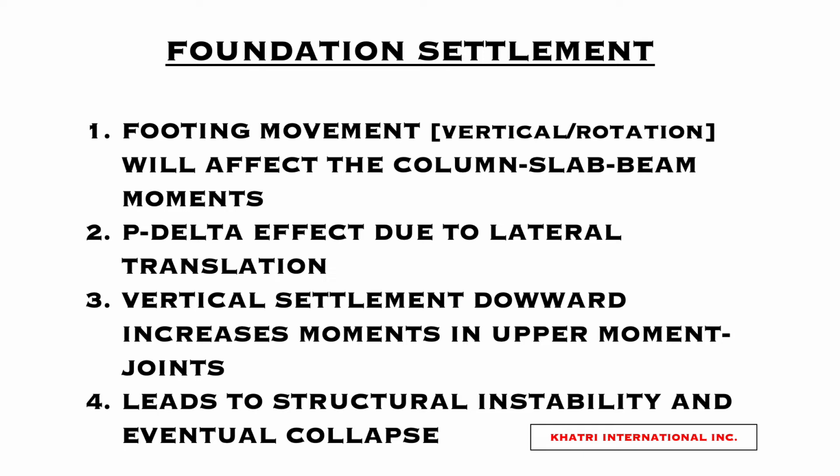How much depends on the building, depends on the type. There are no rules of thumb here. This is new territory that we're in. We're looking at something that really hasn't been examined before, and it requires some attention. And the best that we can do as structural engineers in working for our clients is to do this analysis on a case-by-case basis and do very accurate measurements of the building to see if the building is moving. If the building is moving, then the next question is by how much? And then we can see whether or not it's detrimental or can it be ignored.